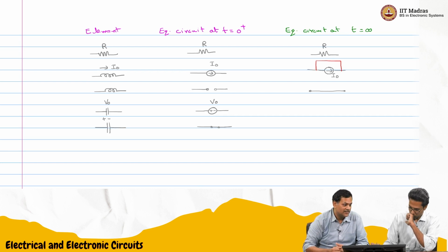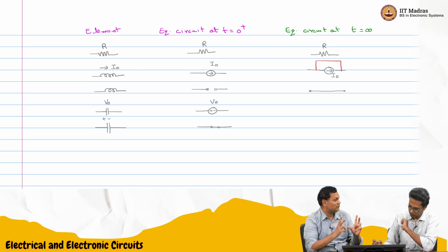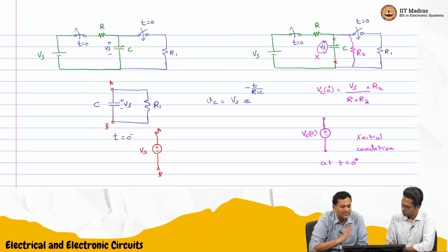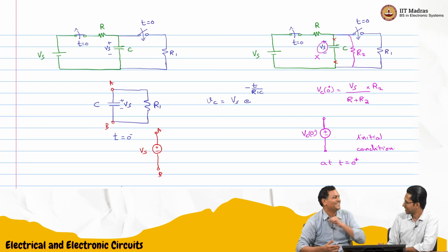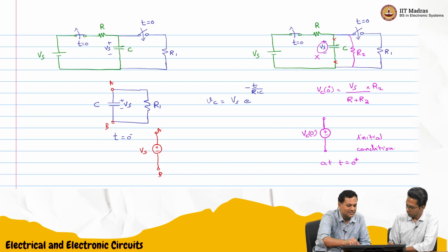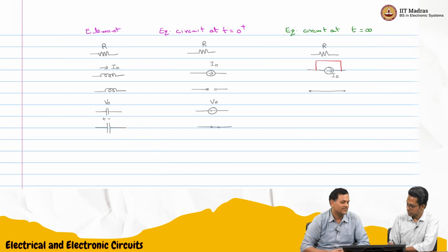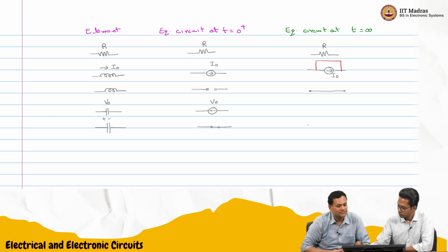How will we represent that? So shall we say it is going to be a voltage? We don't want the effect of that voltage, right? We can refer to the circuit, saying finally there will be no current through this. So it should be an open circuit. Then we will represent this as the voltage source in series with an open circuit. Something like this.